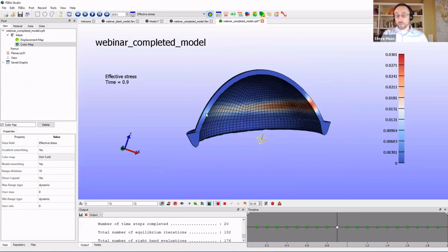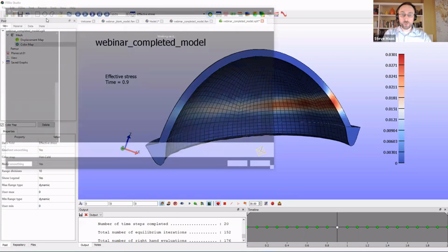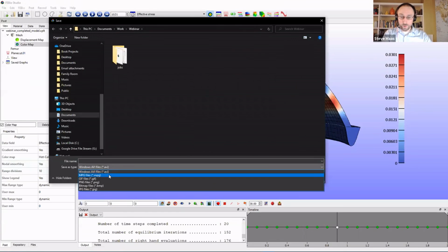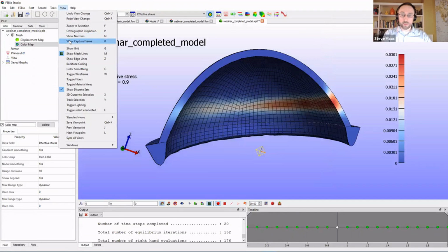You can also make screenshots and video recordings of your model. And the way you would do that is go to record. So let's make a quick video recording here. We click on record, click on new. Oh, actually, before I do that, I have to turn on the capture screen.